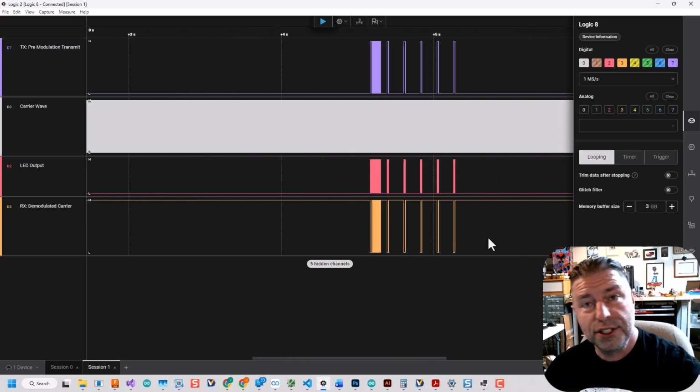I'm not going to go into all the software of how I encode or decode these. They are available in the IRTX and IRRX code files on GitHub that show the state machines that I created. Again, these feed up through I2C to the Arduino libraries on the Serial Wombat protocol that you can command from MicroPython or Python or whatever to offload all of this capability from your main microcontroller, so it doesn't have to worry about creating these signals or decoding them. They simply turn into queues that you access over I2C.